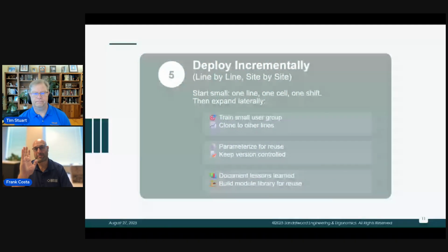We've talked about deploying ad nauseam. Again, the parameterization that you developed at the beginning, your first steps, that's what you want to go through and use. Nothing hard coded. The beauty, if you're using a UNS, is you can use those top level topic domains and basically use repeaters in your views in Ignition to enumerate what's underneath them and show them. You add a new tag underneath the parameters, it'll show up automatically.